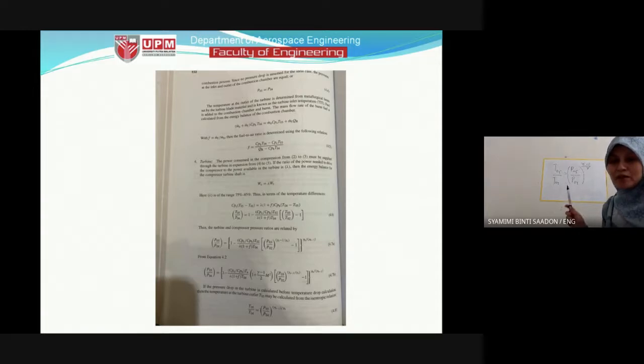We use the same gamma. Otherwise, if it's given, like the CP just now, because sometimes after the exit from the combustion chamber the CP and the gamma change because now we have added fuel. But here, for the ideal case, we assume that specific heat and gamma stay the same. So gamma is still 1.4.